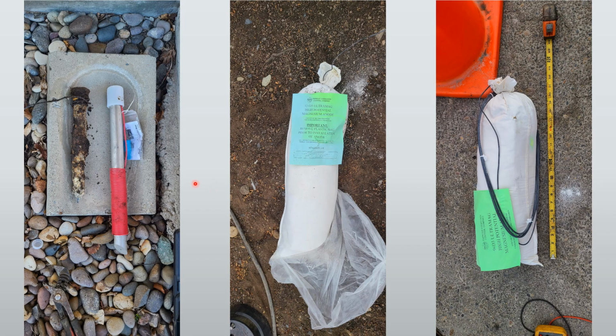These are just some example pictures of anodes that have gone on the ground. Got our spike anodes on the side. This is a 32-pound high potential magnesium anode, freshly out of the bag. Again, that would be wetted before we put in the hole. This is just another 9-pound anode on the side. You can see the shape of the magnesium anode starting to come through, even a little bit of a hole. It's probably rough taken out of the package. It looks like it's about 20 inches.